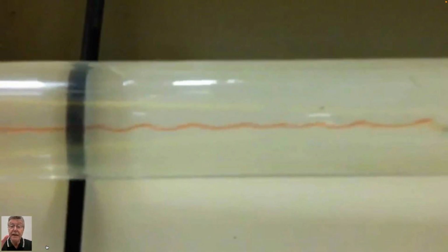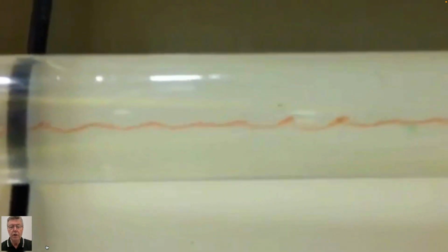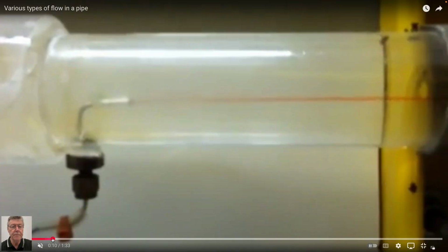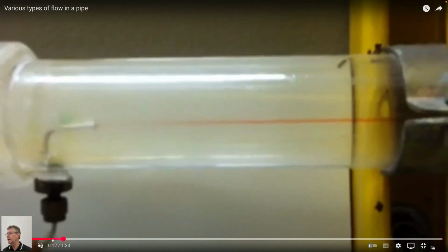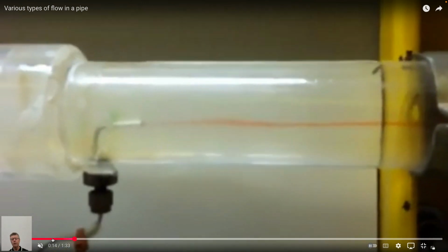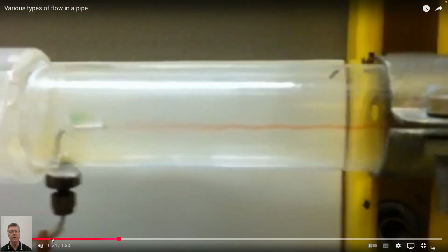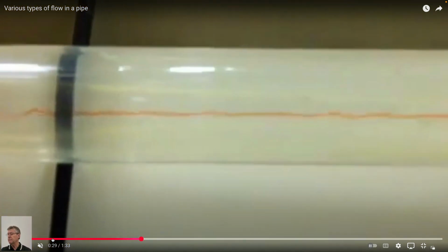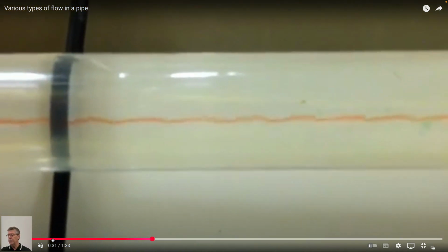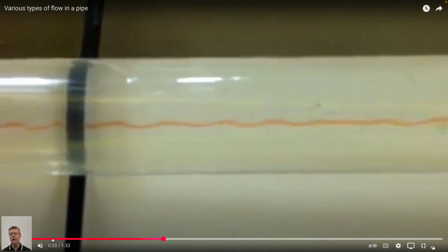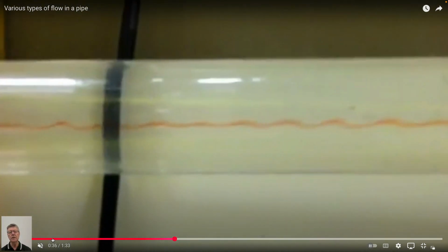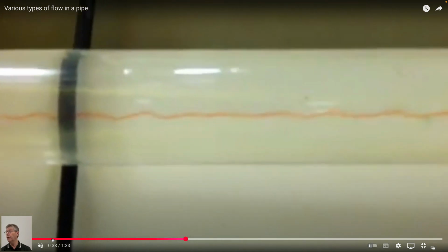So this must be a velocity big enough to get turbulent flow. It's no longer a straight shot. Upstream it was straight, and so it takes a while for it to get this turbulent flow as you go downstream. But it must be turbulent all the way, but it just hasn't fully developed until you get further away from the injection point of this dye. So this is just a manifestation. These ripples are a manifestation of vortices which are present in this, and those vortices are representative of turbulent flow.